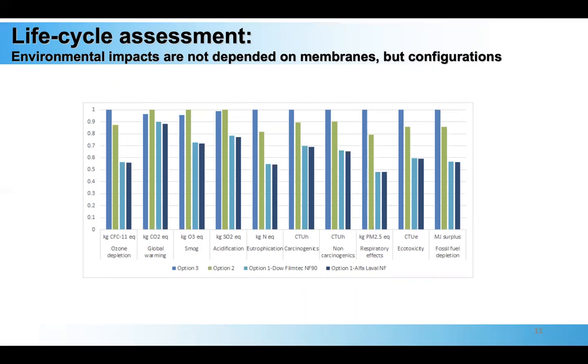We considered a multi-stage membrane configuration, with 2-step or 3-step removal of nitrogen and phosphorus in separate steps, and then combining the concentrates for struvite recovery, and also a third option, removing the excess of nitrogen for organic nitrogen fertilizer recovery.